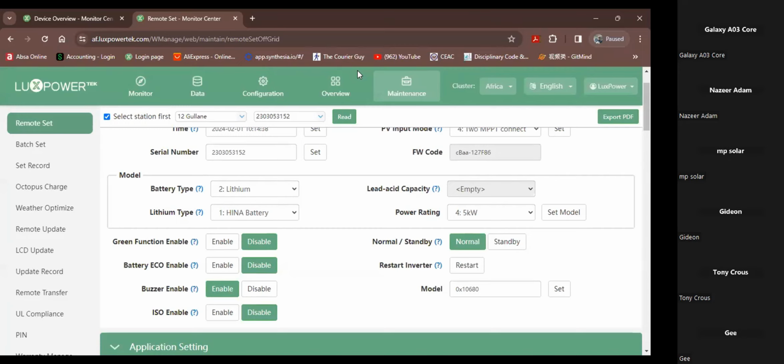So to calculate the capacity of the battery, you multiply the nominal voltage by the rated current. So the B3 is 48 volts multiplied by 75 amp hours, which gives us a 3.6 kilowatt-hour battery. But remember that the B3, the old B4850, the A48100 and the BX5100 are not 1C batteries. They're 0.5C max continuous. So on a B3, for instance, we're doing 3.6 times 0.5. That gives us 1.8 kilowatts of max continuous discharge power.